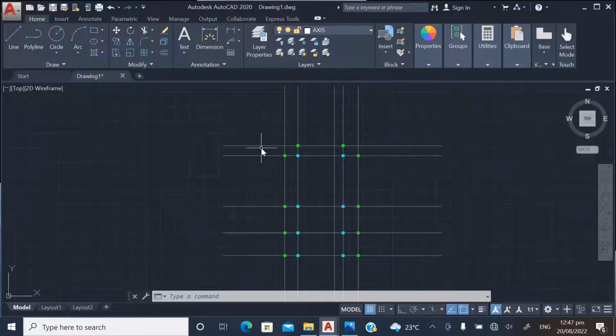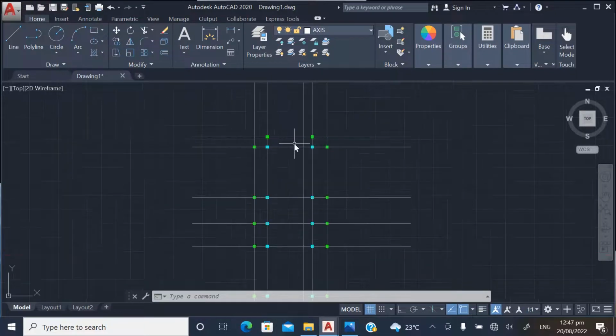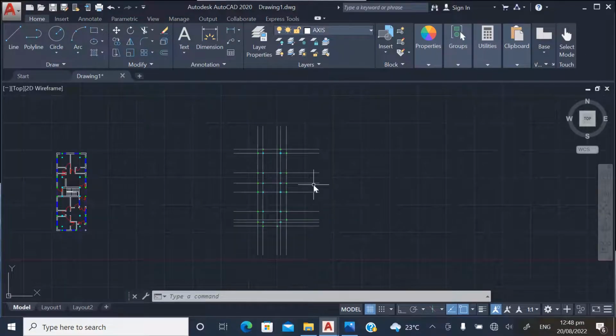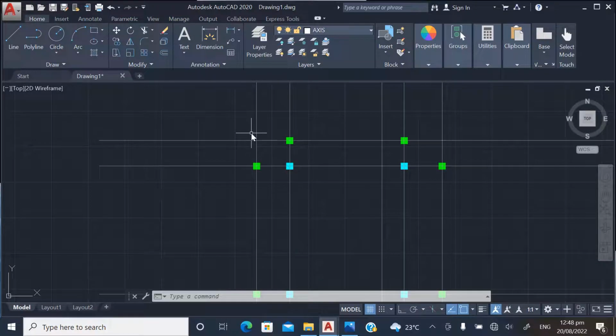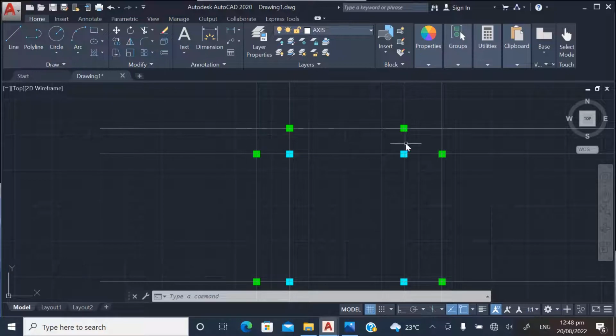So the next thing we do now is, because I want us to know the beam positions, where we have the slabs and all that, I want us to do everything on the AutoCAD here before we go into the modeling of the members in Robot and Prokon Structure. So now we are going to draw lines for our beams.